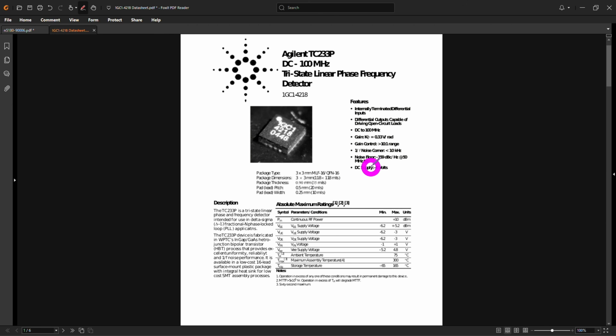Now, there is a theory here that maybe this has degraded to a point where the gain of the phase detector, this K, has drifted from its nominal value. Now the KVCO itself is not constant, and it may be that in some situations it just doesn't meet the locking condition anymore. The loop is just not stable anymore. That is possible. Now I know I've talked about that I'm going to do a video about PLL theory, which would make all of this make a lot more sense, but for the time being, the value of this K and the value of the KVCO plus a whole bunch of other parameters fit into the feedback equation of the PLL and is very important for its stability.